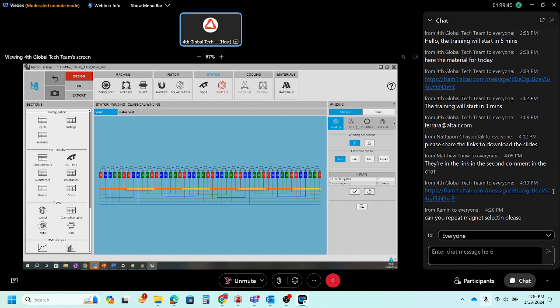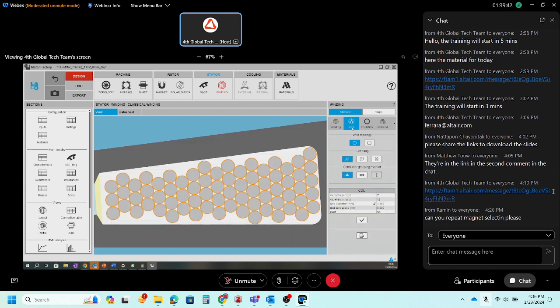We can now fix the problem here, going in the coil section. So under coil, make sure that wire topology has circular connection. Okay, here, circular one. The slot filling is orthocyclic, and the grouping method is grouped.